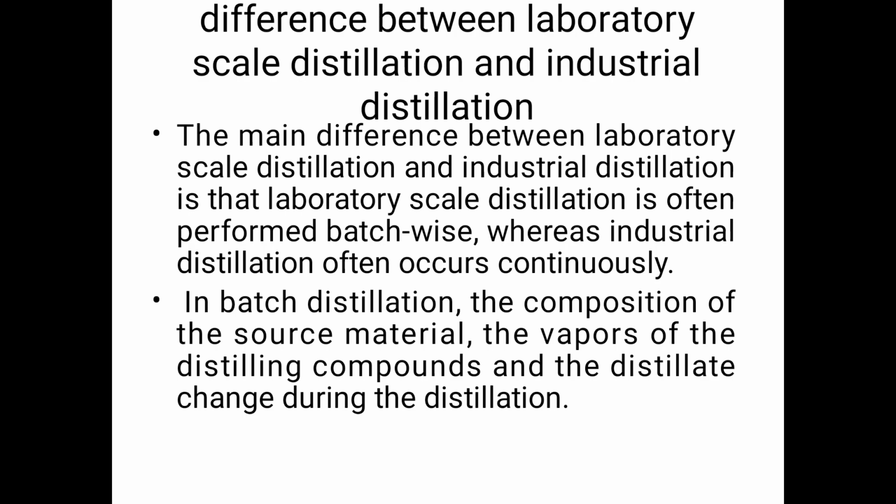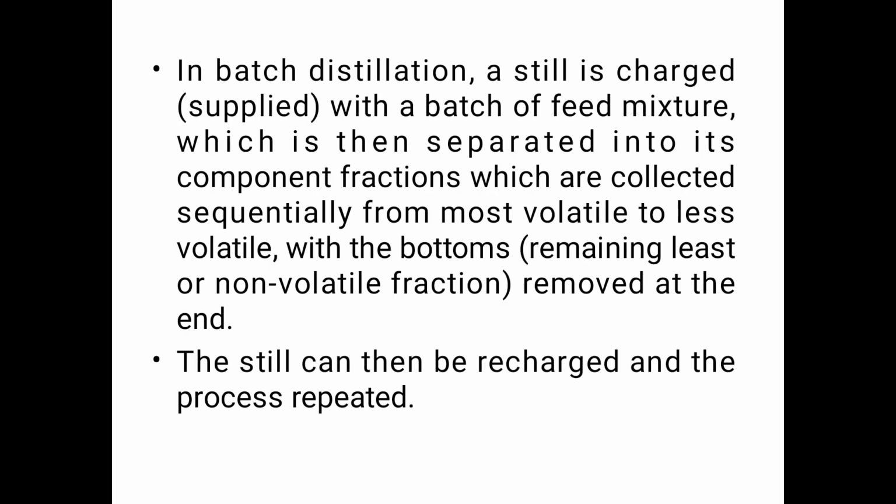What will happen in batch distillation? The composition of the source material, the vapors of the distilling compounds and the distillate change during the distillation process. In batch distillation, a still is charged or supplied with a batch of feed mixture, which is then separated into its component fractions, which are collected sequentially from most volatile to less volatile, with the bottoms, the least or non-volatile fractions, removed at the end.